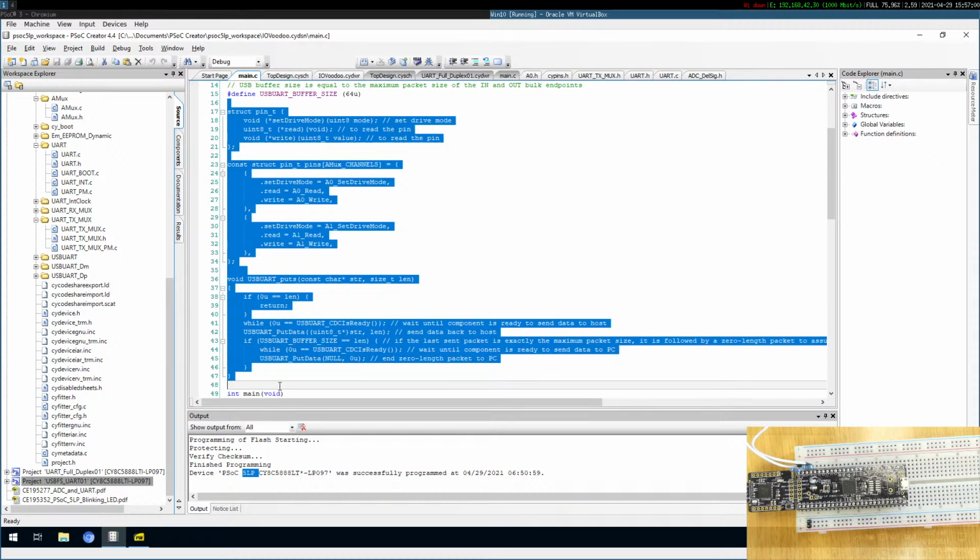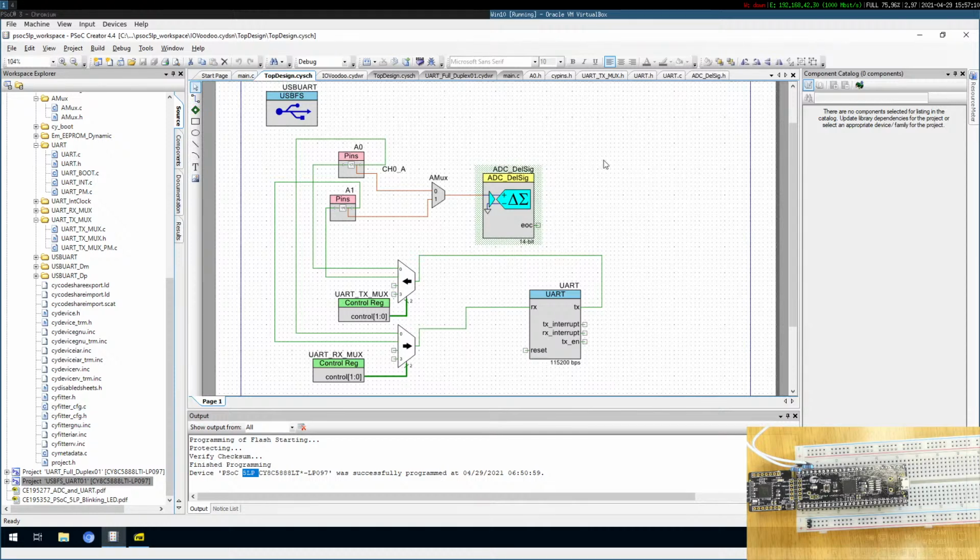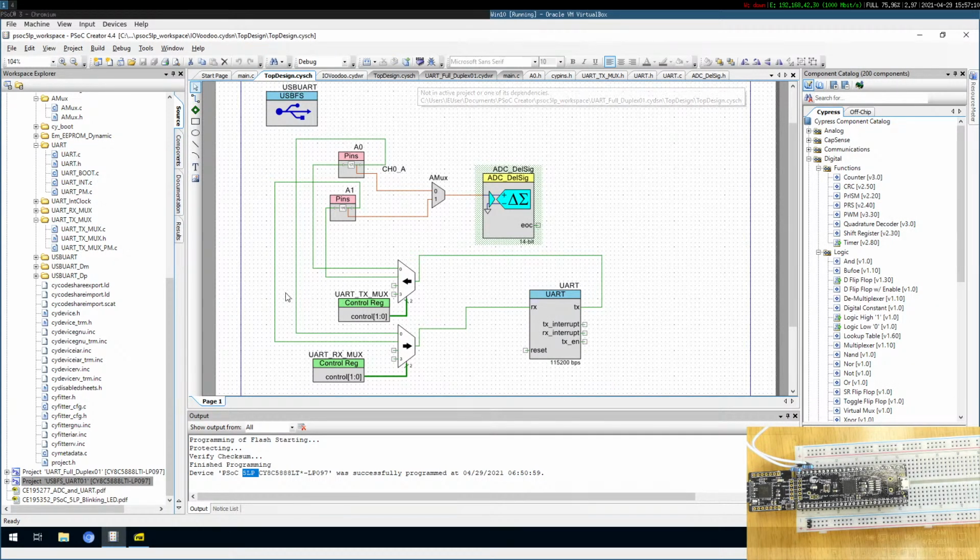I'm really not fond of having to use Windows for writing the code. Probably I just have to use Windows to generate this schematic one time. Once this is generated and all the source code has been generated, which I need, I kind of think I'm able to compile everything under Linux and then use ARM GCC and makefiles.